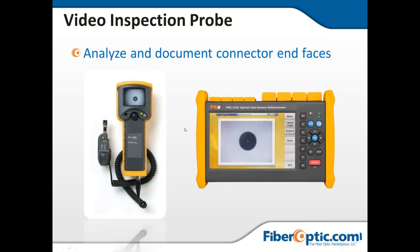There's a way of, if I didn't have a microscope, I've actually been able to clean connectors or tell whether they were dirty by looking at it and detecting scratches or debris on the end of the connector. So just very, very good ways of using a visual fault locator. So if you can get it built onto the OTDR, why not?